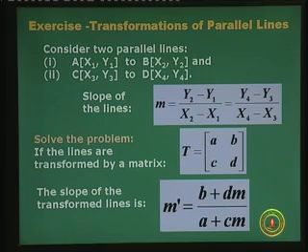I will also ask you to take another exercise to find out, if you have two intersecting lines and their intersection point is computed, after transformation you get a new point of intersection, and the entire object which is transformed by an equivalent transformation matrix, the corresponding intersection point is also transformed by the same T. This is derived from the law or the concept that all points of a rigid object are transformed equivalently by the same transformation matrix,